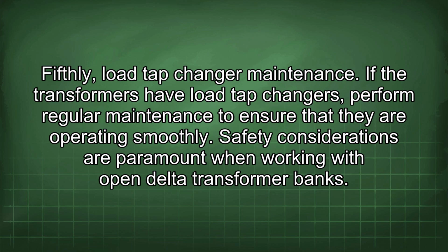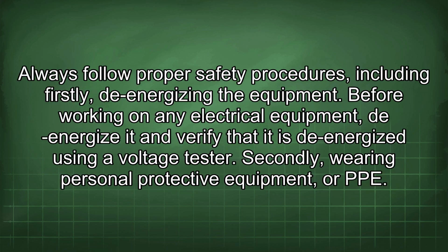Safety considerations are paramount when working with open delta transformer banks. Always follow proper safety procedures, including, firstly, de-energizing the equipment. Before working on any electrical equipment, de-energize it and verify that it is de-energized using a voltage tester.